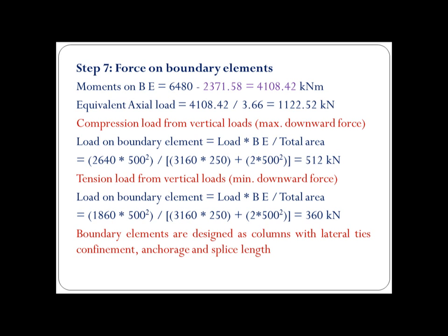So this is given by 6480 minus 2371, so 4109 kilonewton meter upon the center to center distance, which works out to be 3.66 meter.